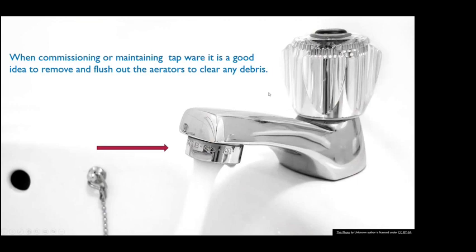In theory, before you test it, you should pre-flush all your pipe work to get any debris, hemp, thread tape, bits of plastic out. Copper. Yeah, little copper shavings. So sometimes people do that. Sometimes they don't, and then they don't turn it on and flow any water through it until they've finished it all. So if it's got a strainer, which most new taps and mixers do, it's a good idea to take that out before you do it so you don't jam it up with shit,